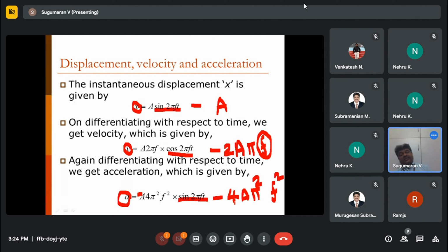If I am measuring normal amplitude, that first gets multiplied by pi square, approximately 10, and this is 4, so it's about 40 times amplitude. It is not just 40 times amplitude. When you measure a 1 hertz signal, it is 40 times. When it is a 2 hertz signal, it is 2 into 2, 4 times, so 40 into 4 times amplitude.